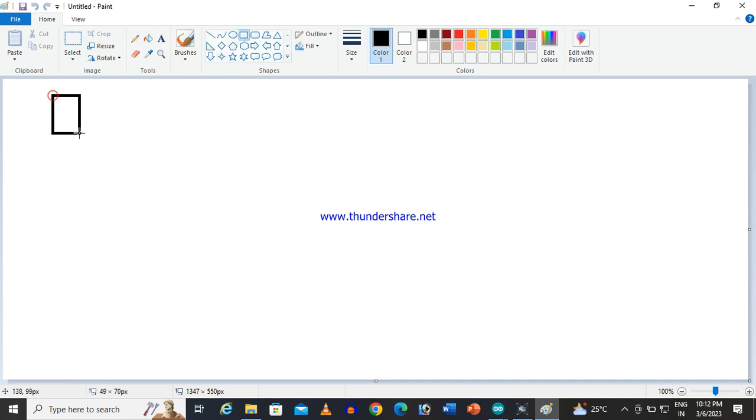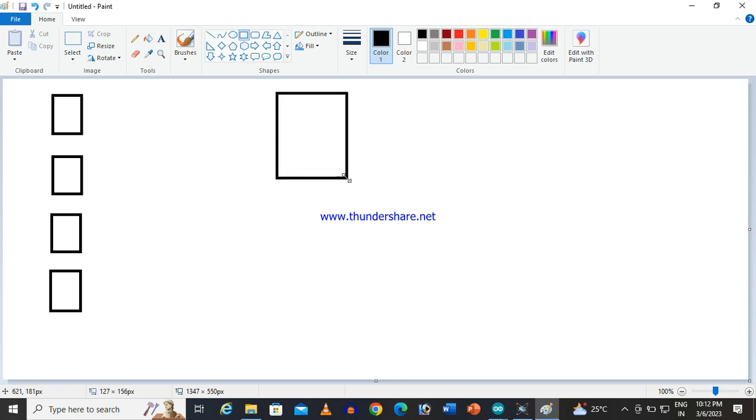Say take this is sensor 1, this is sensor 2, this is sensor 3, this is sensor 4, and these 4 signals, say thermocouple or RTD, are to be captured in a controller using a single ADC.